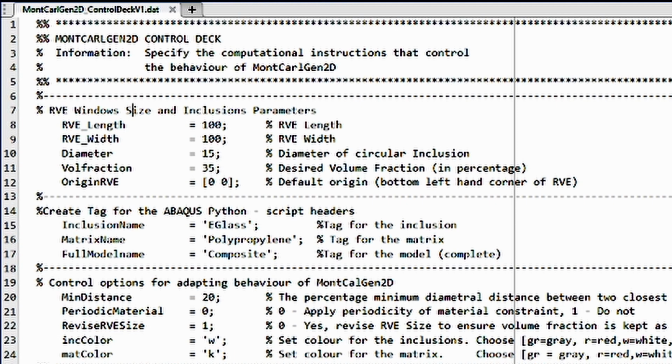So this simulation that we want to do, we want to set up a porous media with a length of 100 microns and a width of 100 microns. This is in 2 dimensions. The diameter that we want to work with is quite small, about 5 microns in this system. And the volume fraction we're going to work with here is, let's say, 20%. So 20% of this porous media is essentially made of voids, and then we can leave all the other bits.